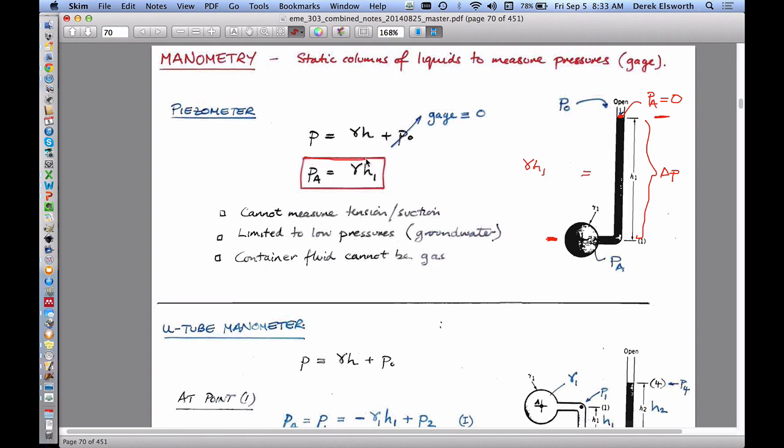So nothing else. And where the fluid is a liquid, density is constant with depth, then we can easily calculate what the magnitude is in the system. If you fill this region here and actually the standpipe up with sand, but so that there was still a connected path through that sand all the way down into the reservoir where the rocks are also sand maybe, then it'd be exactly the same calculation you've made.